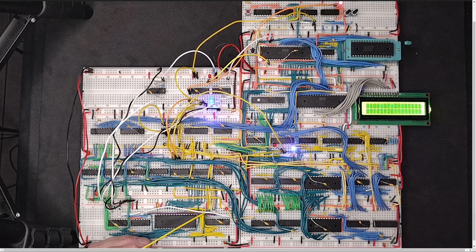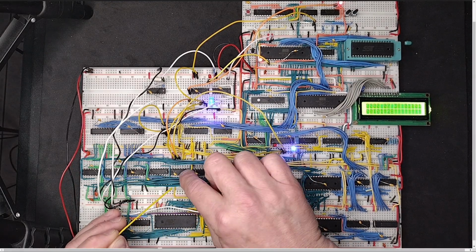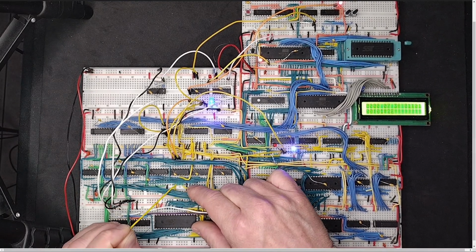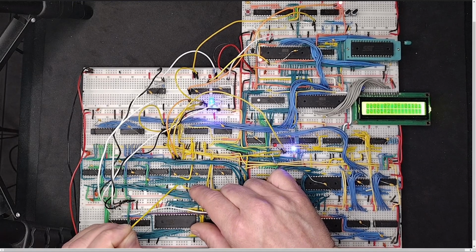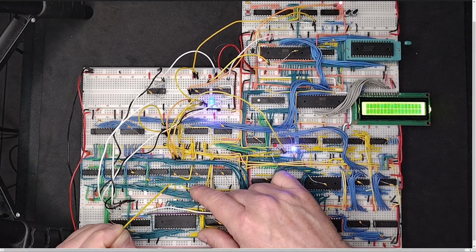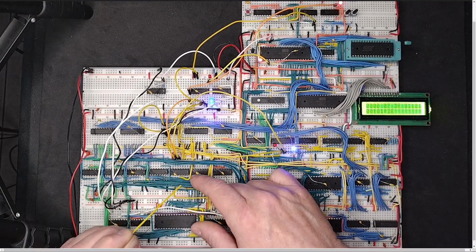So that's this signal here. So this signal here runs up. This is the vertical blank start signal, and it runs into this NOR gate flip-flop, and I've created that by running the output of gate 2 into the input of gate 1, and then I'm crossing the output of gate 1 to the inputs of gate 2.